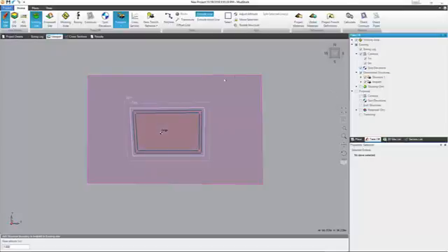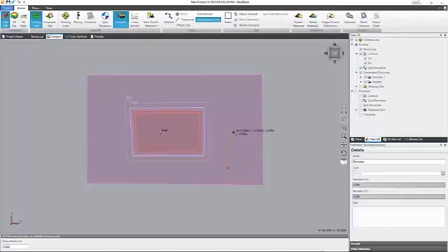Okay, and then let's say we want some footpaths down at the bottom level here, but we can use the one line as a guideline. So we can do extrude input line now, and let's put that altitude down to 0 meters, as we know that's where that is. And let's just put in a footpath that does something like that.